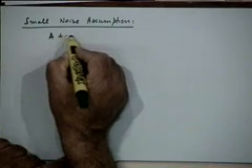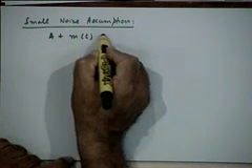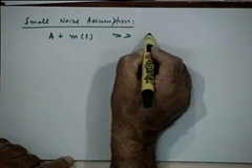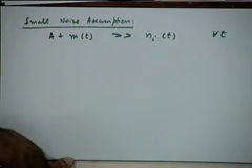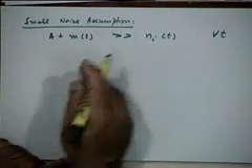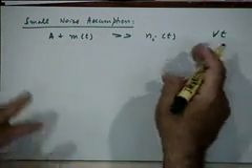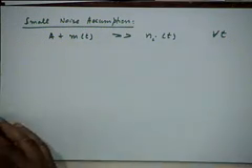So, the small noise assumption will imply here that A plus m(t) is much greater than n sub i of t for all values of time. Although n sub i of t is actually random, so making this kind of a statement is a loose statement, but I think it is convenient at this stage to make it.